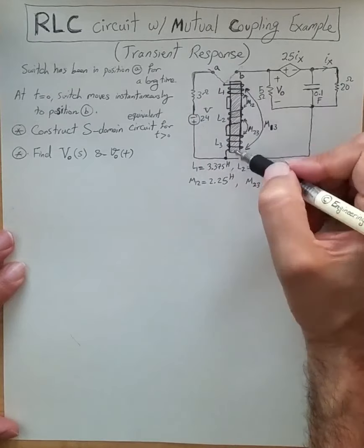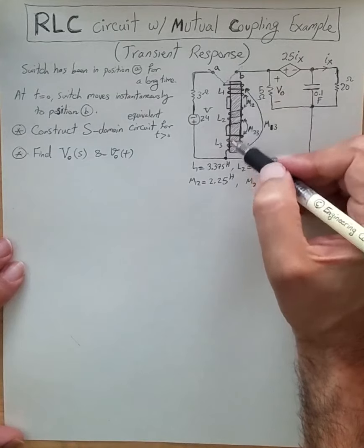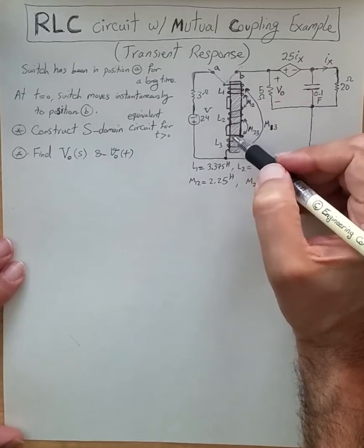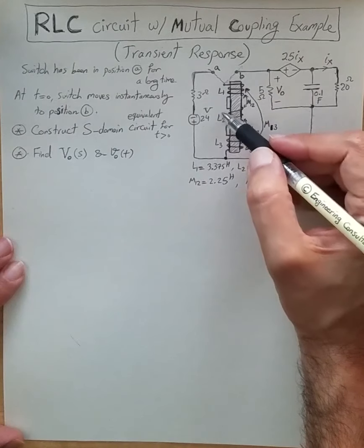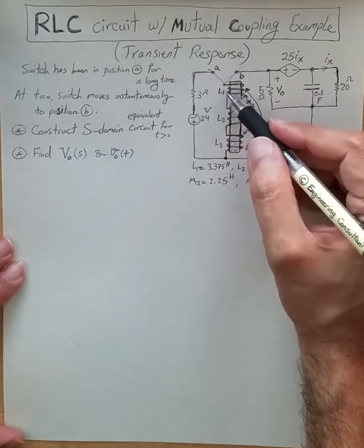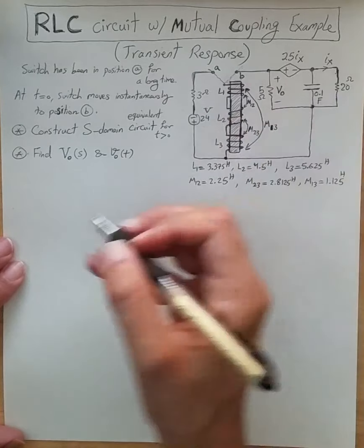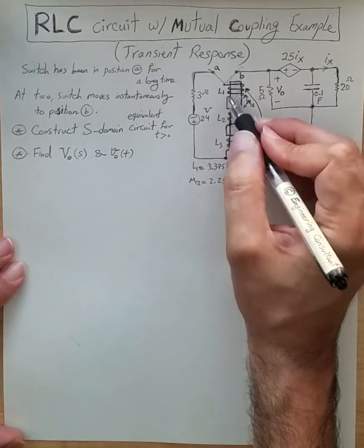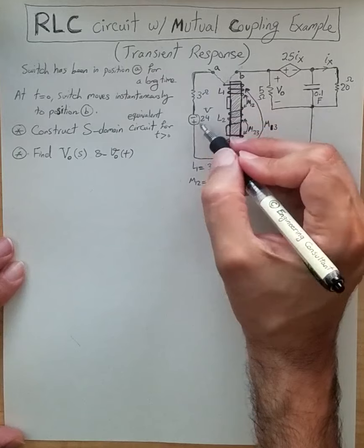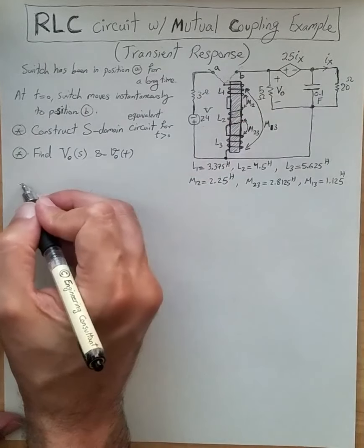Because the inductor is an ideal inductor, meaning there is no internal resistor involved, when it reaches a steady state the voltage drop across the whole inductor is 0. Therefore, we can say that all the 24 volt going through the inductor and coming back just drops across 3 ohm, and therefore